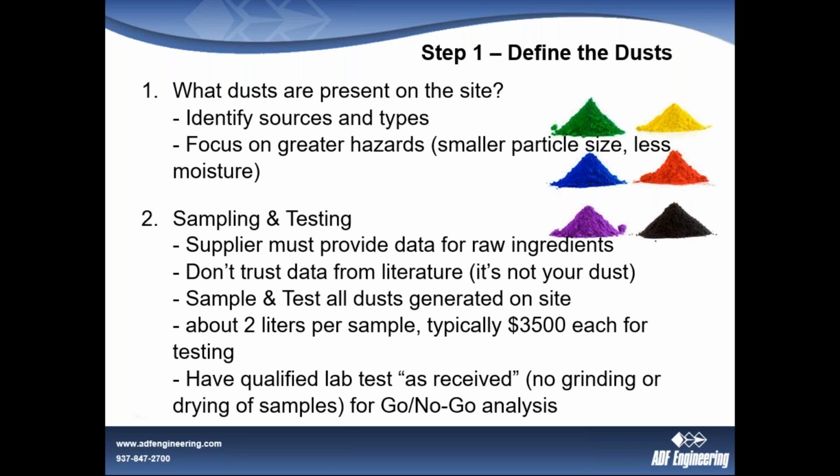However, if you are bringing in a raw material and that raw material that you receive is the combustible dust, then it really falls upon your supplier to provide that data, because one of the requirements of NFPA 652 is that the dust data must be included on the SDS. So in other words, they have to provide you with that information. And conversely, if you are providing combustible dust containing materials to your own customers, you need to have this data defined on your product and included in the SDS.